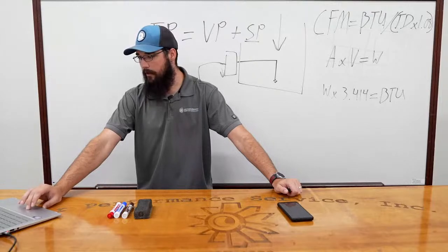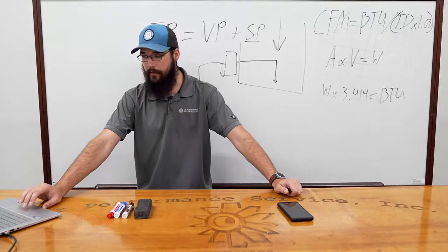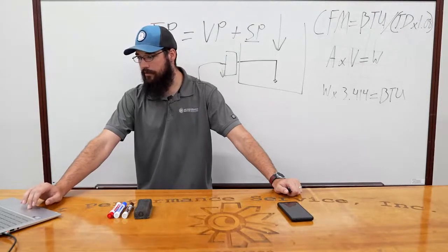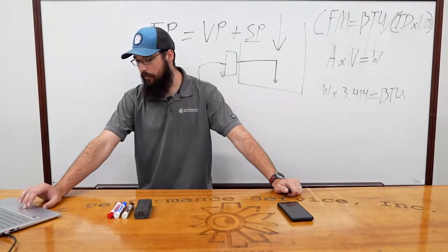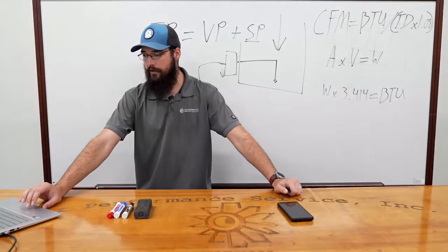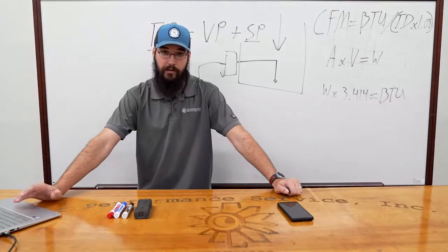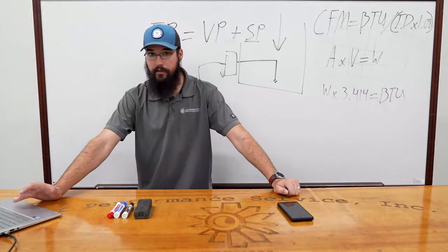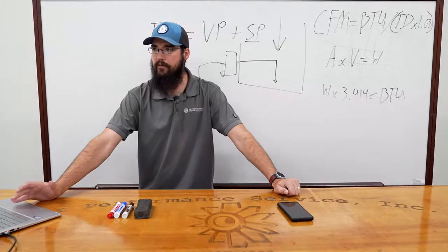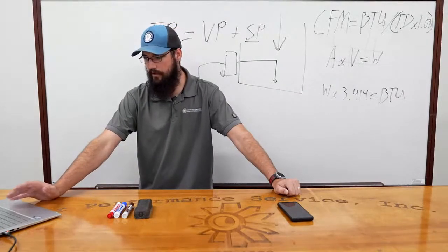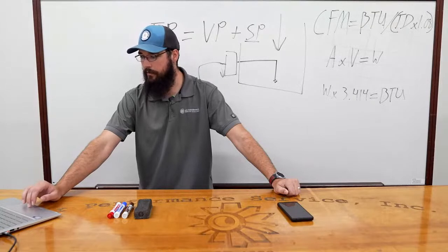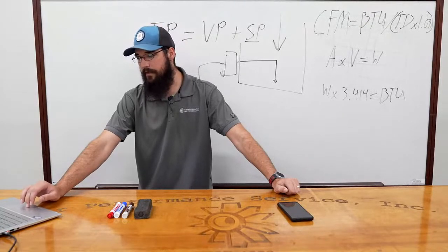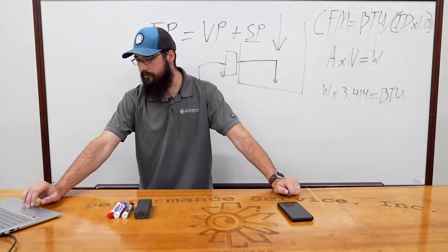Something I want to point out is, if you look at both of the pulleys, and just below them in red lettering, you see RPM. All the other numbers, don't worry about those right now. Let's focus on just the RPM. I have it set to where the small pulley reads 1750 RPM. That's a very typical motor we see on our side, either 1750 or I think 850 is an alternative. Anyway, 1750 is the most common. So that's going to be a set speed at that motor.